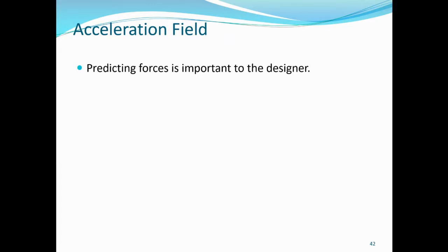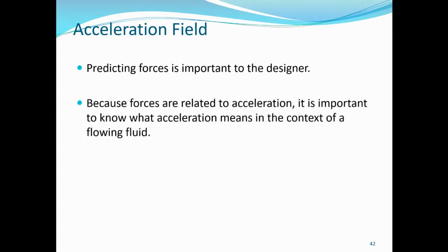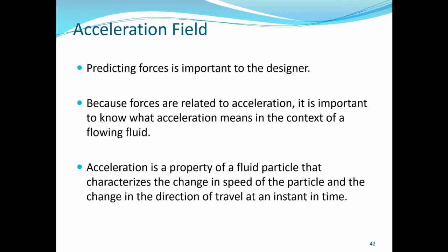Predicting forces is important to the designer. And because forces are related to acceleration, it is important to know what acceleration means in the context of a flowing fluid. Acceleration is a property of a fluid particle that characterizes the change in speed of the particle and the change in the direction of travel at an instant in time. So the acceleration is simply dv/dt.